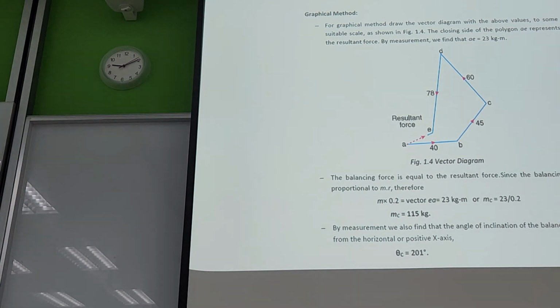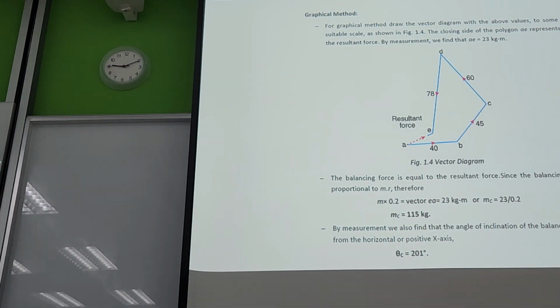Any doubt or anything you have? Any questions? No, that is just a drawing error. If you use a bigger scale, then your error will be reduced. So what you are doing is you are calculating all the forces, then you are just doing the balancing force here. So making the sum of the forces 0 because the polygon is closed. The force polygon is closed.